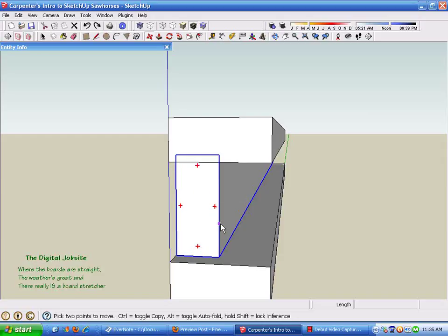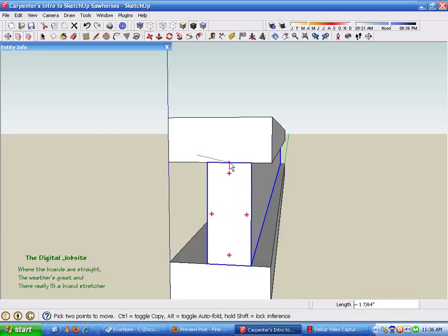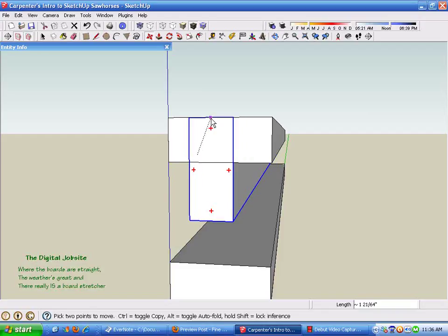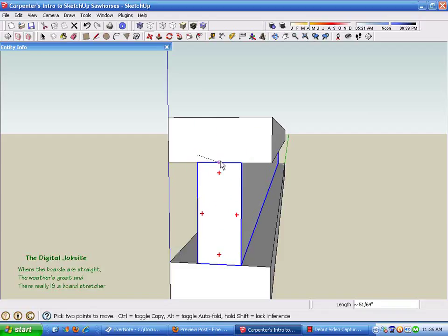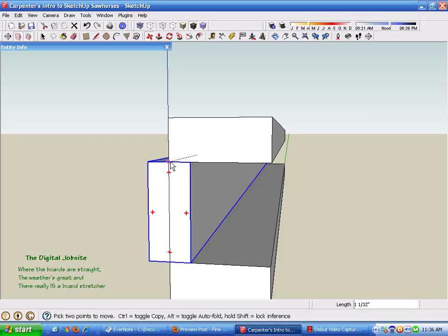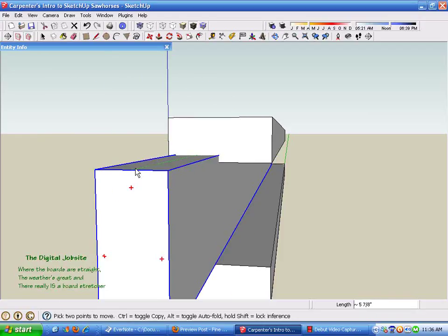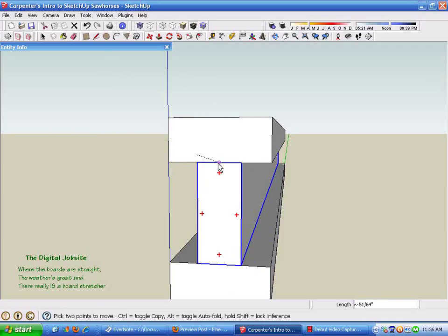So in the 3D modeling world, it's important to pick things up and drop things and measure things from the point you want to. You can't just grab this 2x4 in the middle with your hand and make it line up. So I'm going to grab it on this top edge when it says midpoint in group, and then I'm going to slide it back and forth on this other 2x4 until it lands on a midpoint. I don't want it on the end. I don't want it out here in space.